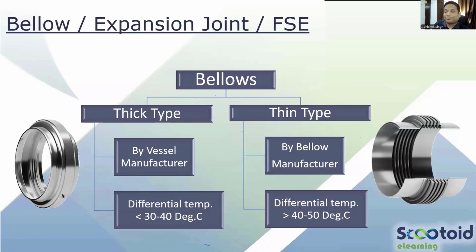And the most important part for the client: the preference most of the time will be a thick bellow. Thick bellows are less prone to failures. They are as thick as the shell, so the chances of failure are very low. Okay, so it is preferred by the client.